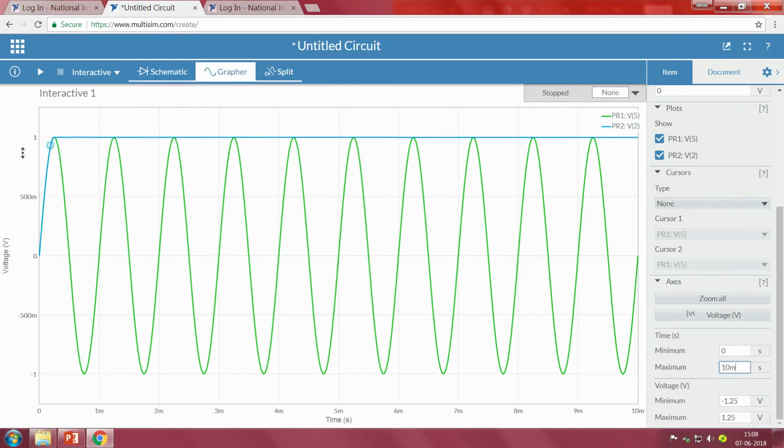Why only to 1? Because the peak input voltage that we applied is only 1 volt, and since we do not have any discharging path, the capacitor stays at this maximum voltage. What if I change my input? If the input voltage is 2 volts, slowly the capacitor starts charging to the 2 volts value. Why do we not see that?